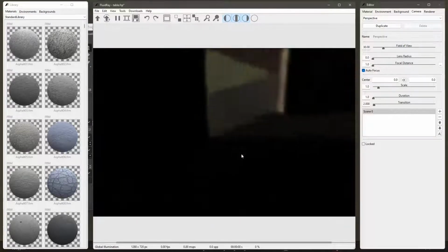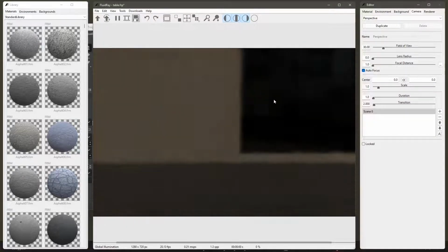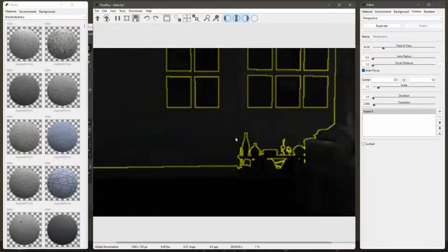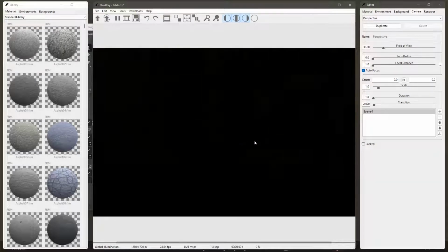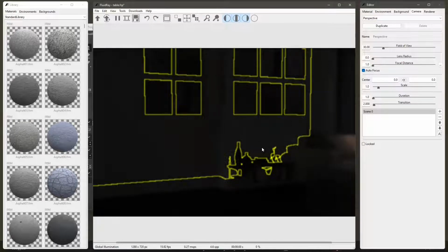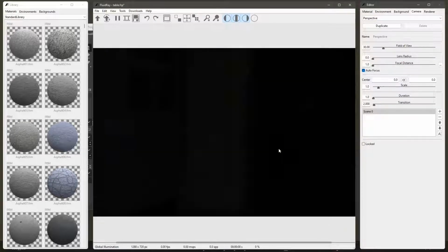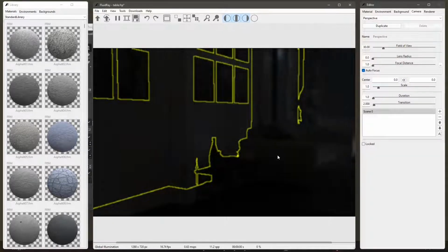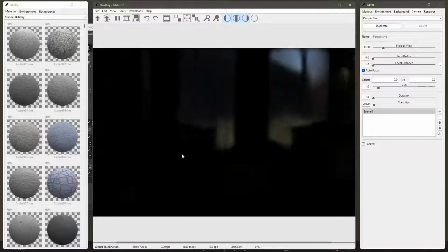Now, one thing also you should export from your application is the camera or many cameras. If you export the cameras, you don't need to navigate around your scene to find out where the correct spot for your rendering is. You just select the camera from the camera tab and that's it. So try to export your scene with the camera included. But we're gonna make some more examples later. We're gonna see some more examples about exporting and importing.